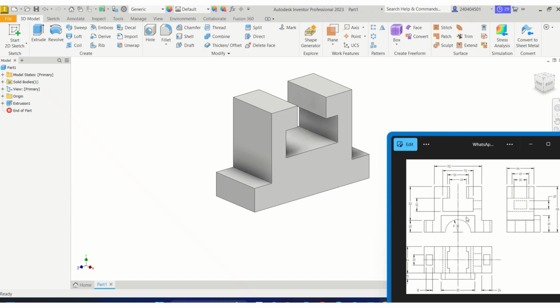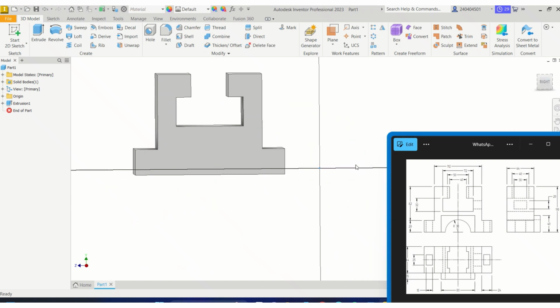Okay. We can produce this likewise on the front view so that we can copy the front view. We have been shown from here that this guy protrudes outside by 15, and the height here is 40. And what again information do we need? Okay, this information here shows us that his length is about 80. So I'm going to come here and create a new sketch on this face.